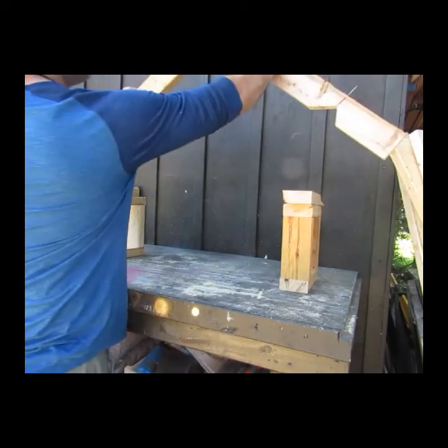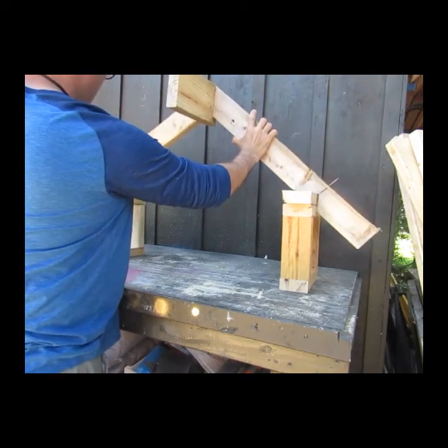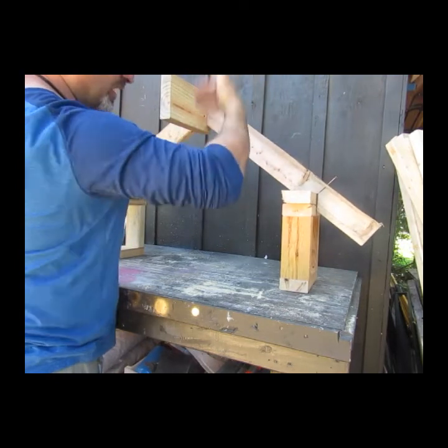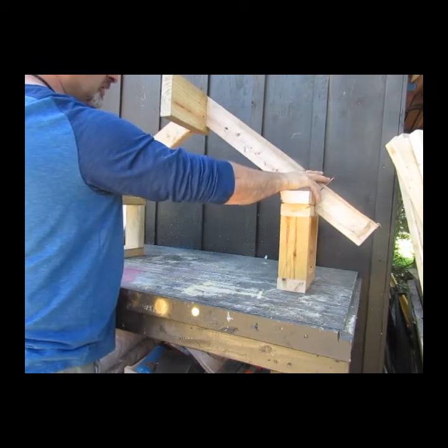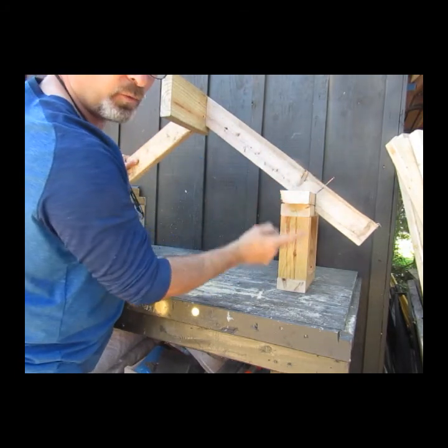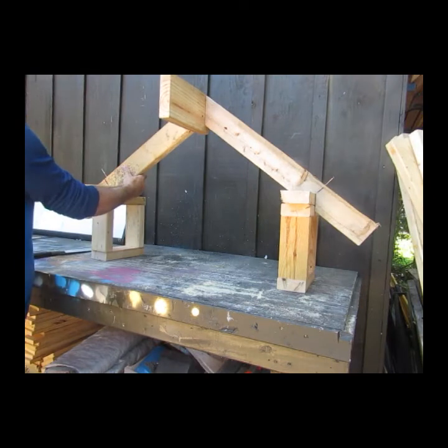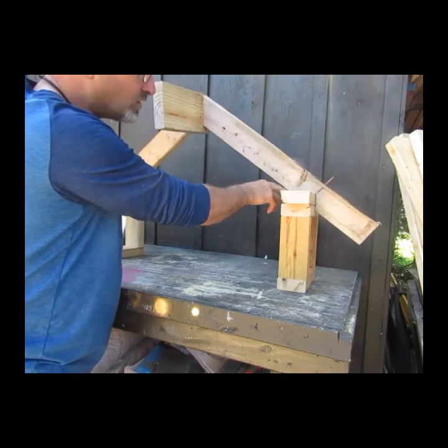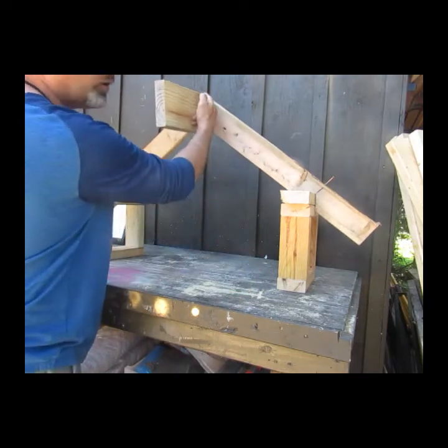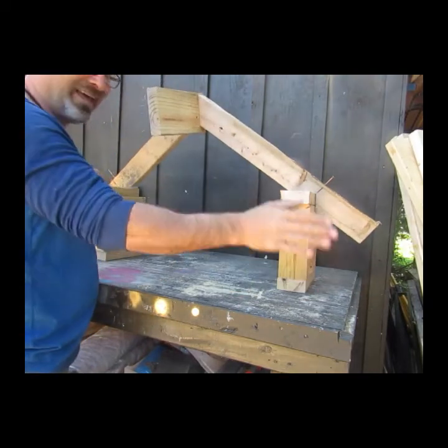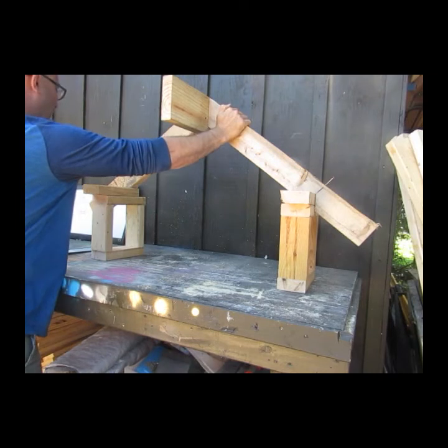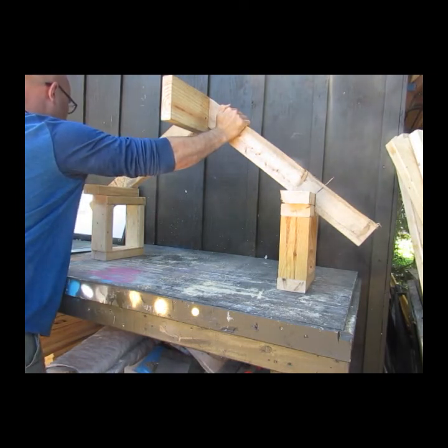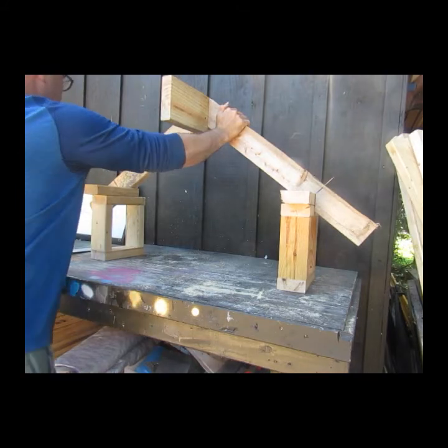So the ridge beam is up, and then you put one rafter up, 16 inches on center, next one, next one, next one. You'll notice the double top plate on the top of our wall. I've got some screws in place already, marking the top of your wall to ensure proper spacing here and along the ridge beam. They have to line up. They can't be on an angle. So what we'll do is drive these screws in. One.